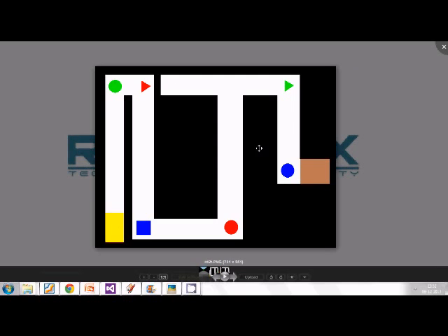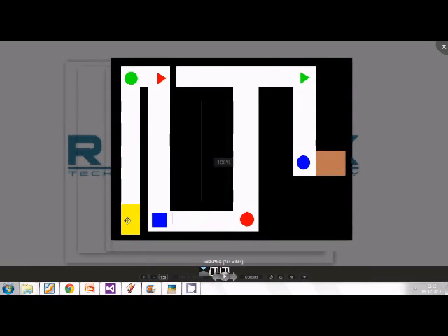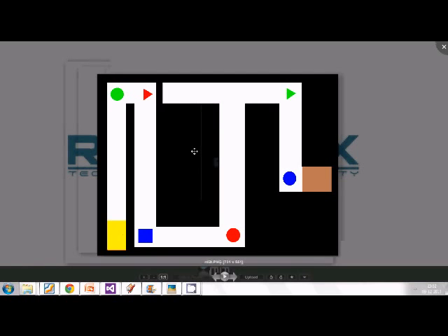Okay. So if you look at this map, the first candidates you'd consider for waypoints would be all the symbols, all the landmarks. They're all points of importance, points where you'll need to do something. And also, of course, the start and ending point. From this 2D image, and here we're talking about 2D image processing and not onboard computer vision, I can consider these landmark patches, and by doing blob detection and color detection, I separate all of this. I will show you a demo of that in a couple of minutes. Then I know these are my various blobs, and these can be my waypoints.